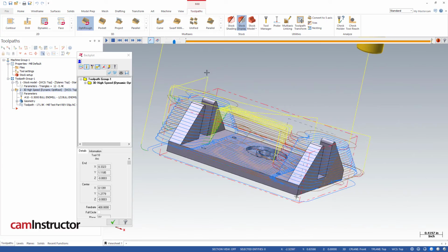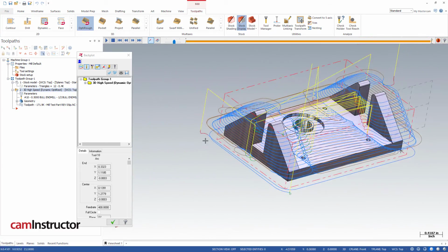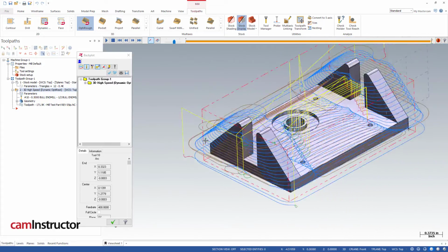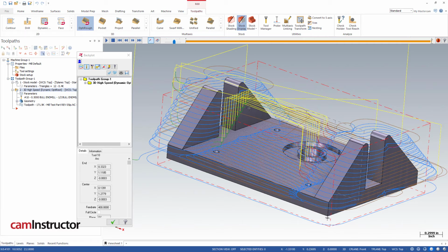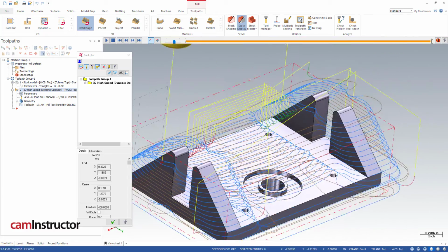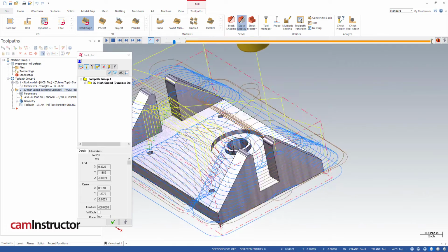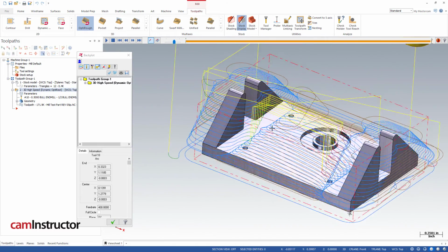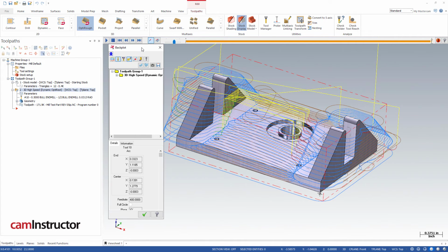So beyond that, we've got some retracting and some repositioning, which I think we won't find much optimization in. So we've got some rapids over here, but these are not rapid transitions. These are rapids for next cuts. You can see on this side of the part, these brown lines, these are the rapid transitions. So we won't be able to get rid of these. We could change them into feeding motion, but we're not going to be able to get rid of those retracts.